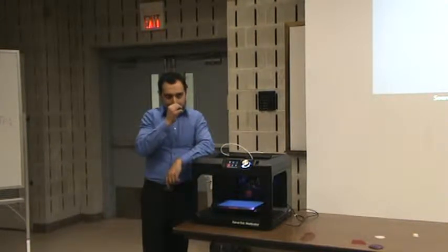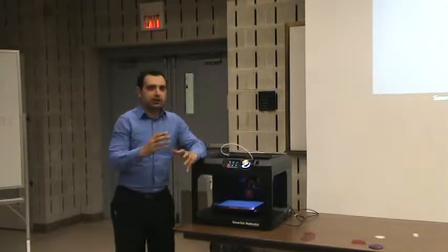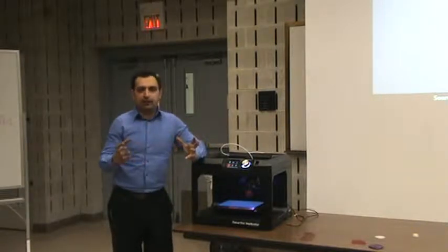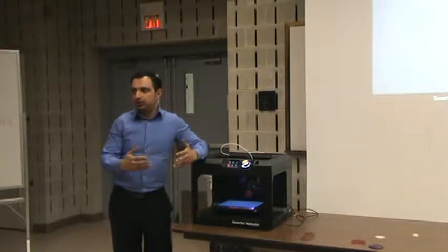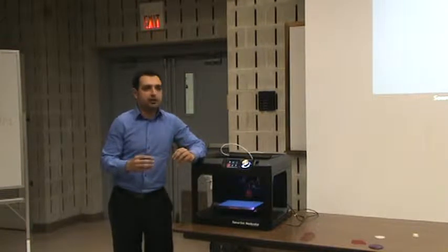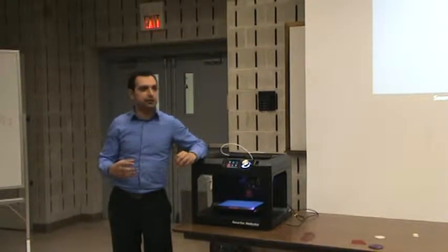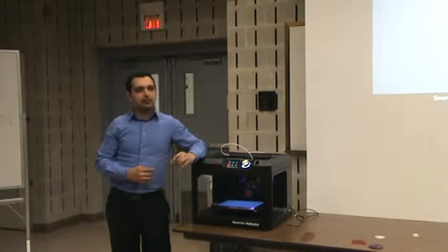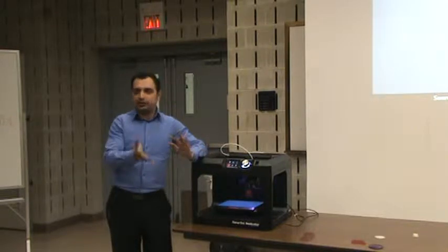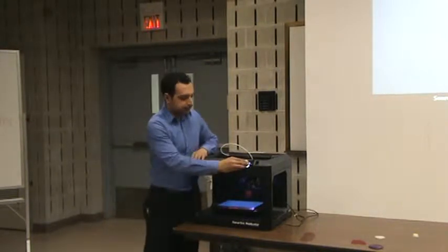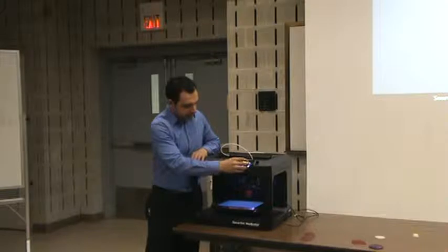Exactly. When you convert your drawing into an STL file and load it there and prepare to print, there's a pre-processing stage where it will tell you the time and how much material it's taking. You can scale up, or if it's too big, you can scale down, and adjust the size. You can change the orientation and print it. You can do very simple modification using that.